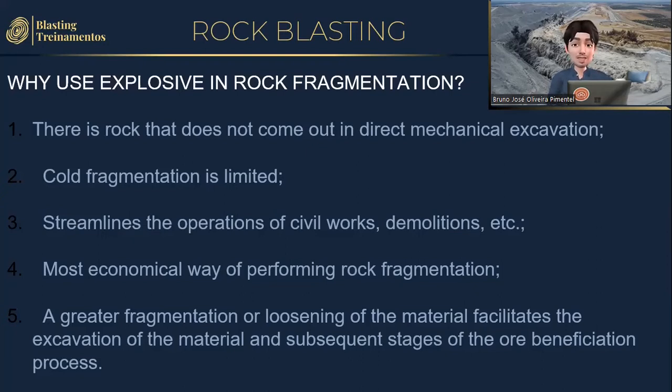For example, a mechanical extraction is mainly aimed at soft rocks, where excavators can remove the rock with some ease, directly. Cold fragmentation, with an expansive mass, is generally used in small quantities, because they do not have a high productivity, that is, they cannot meet other production demands, or the types of extraction through the use of diamond wire equipment. Usually they are only useful for cutting rock blocks and do not have high production rates or perform other types of extraction. Thus, each technique has its limitations in the scenarios in which they are applied, and when they are not efficient, the single most comprehensive technique, of course, if performed correctly, is the technique of blasting rocks with explosives, where we have the most flexible technique of all in the use of explosives.